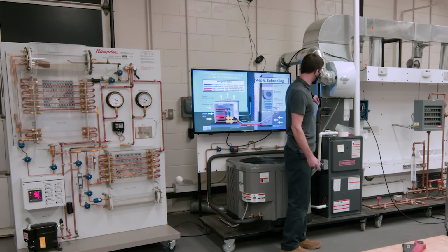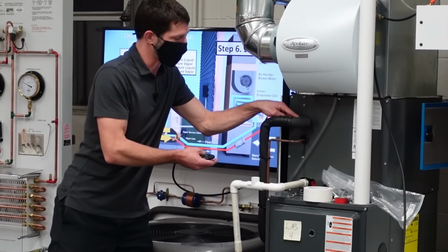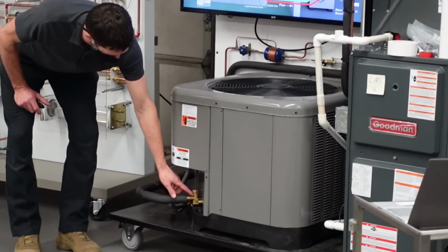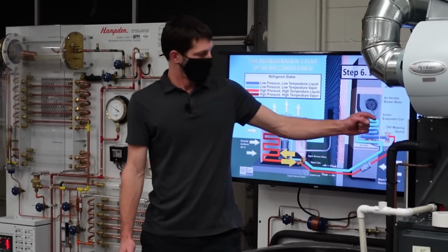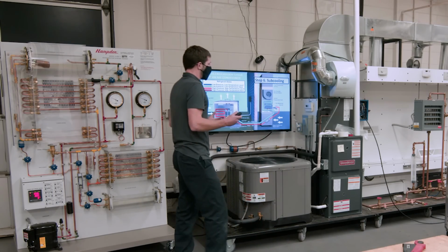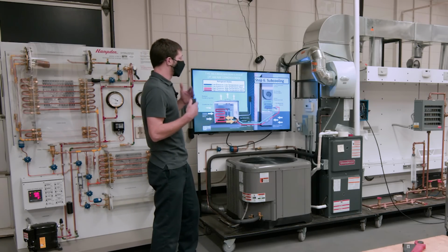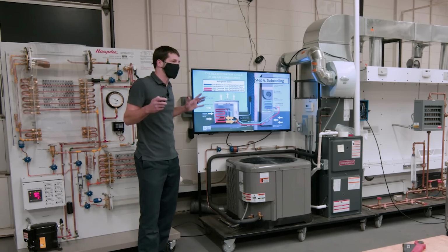Oh, I'm sorry, there's no port to measure over here usually on a standard system. So this would be superheat if you measured your pressure and temperature here. But since you measure it out here, it's called the total superheat. It takes into consideration the tubing running in the ground or pressure change just due to maybe a high vertical run or long line set. So any questions so far?